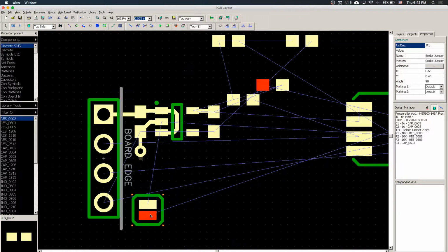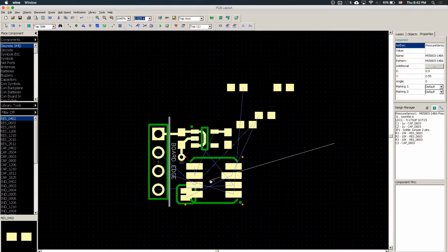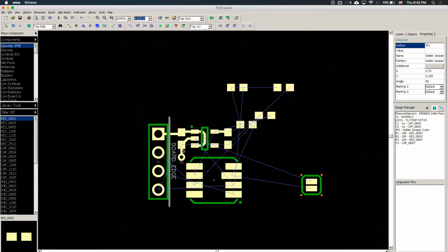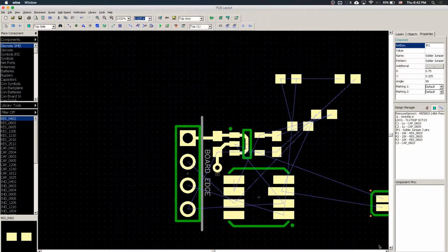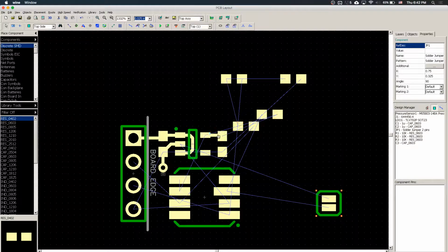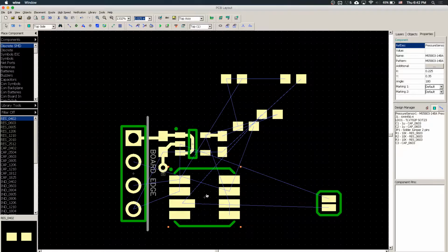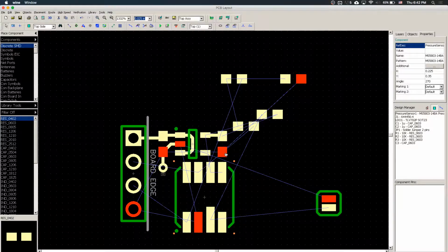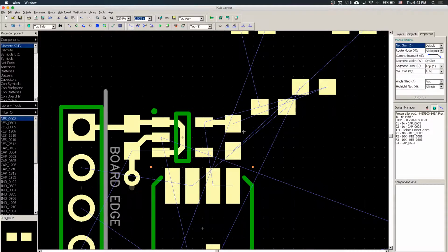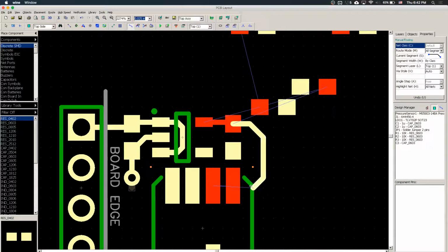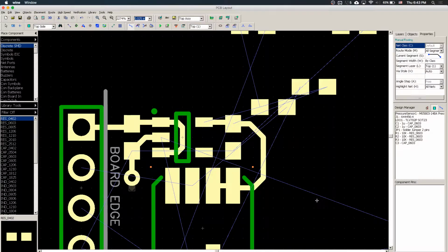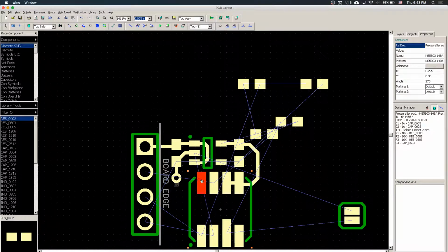So this is our jumper cable, and we're gonna try to place this here. So we can highlight our output. This net is where we're gonna put our VCC. So I will be connecting our VCC like that, and SCL is this pin. SDA is this pin, and SCK is this pin. So for the two resistors, I will be connecting SCL and SDA.